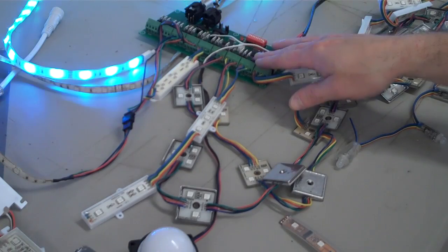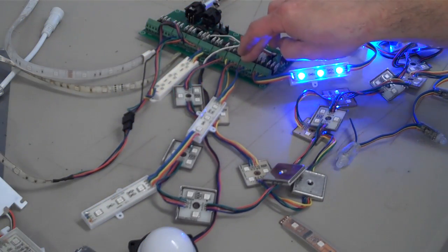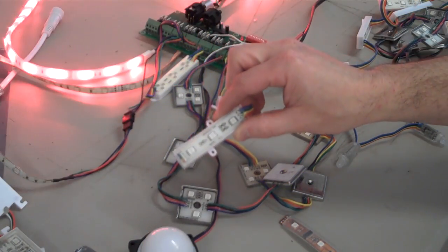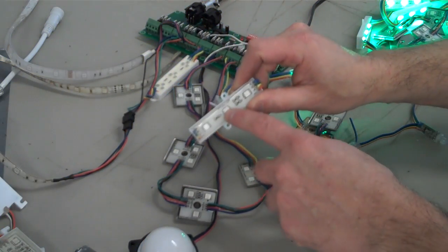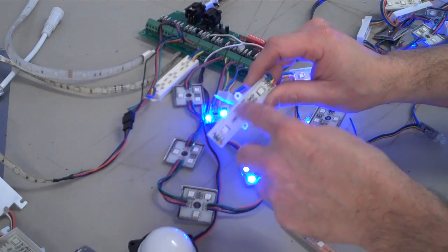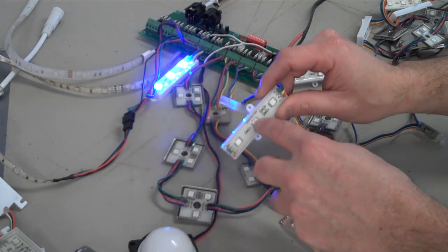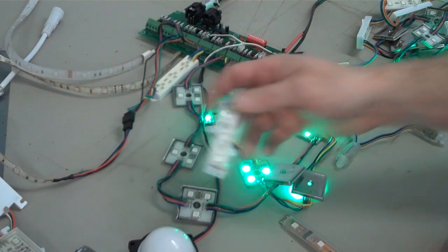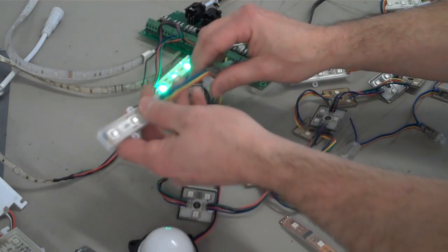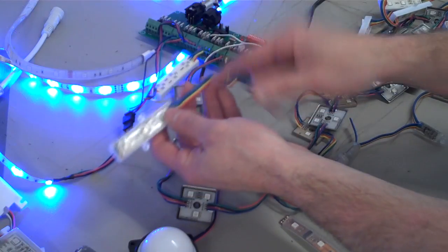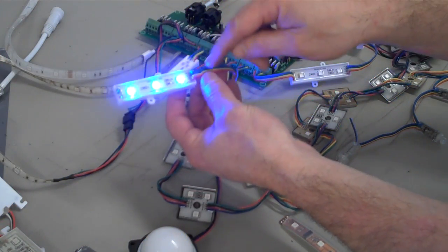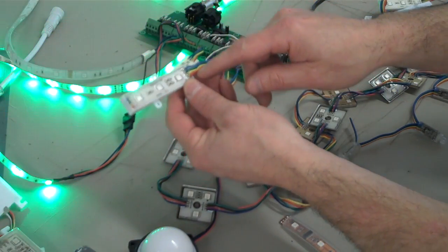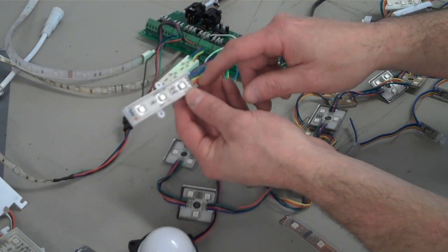But in RGB Basic, what we have is we have a DC controller and we have RGB lights. Now, the difference between your traditional strings and RGB lights here are that, of course, as I mentioned before, the RGB allows you to color mix these. So because the lights are so close together, we can control them to make them red, blue, or green. Now, these are different from your traditional displays because these are DC, and as such, we have 4 individual wires. We have a red, blue, and green wire, and we have a shared positive or common anode.